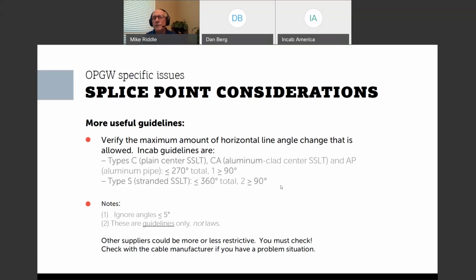So what you would want to do is use a downlead clamp to prevent the cable from moving freely and abrading. And are they allowed on distribution due to the bending radius? In general, the bending shouldn't be a problem even on a distribution line. But yeah, it's something you'd have to check. Each cable vendor is going to have a recommended minimum bending radius, and as long as you don't violate their restriction, you're okay on that.